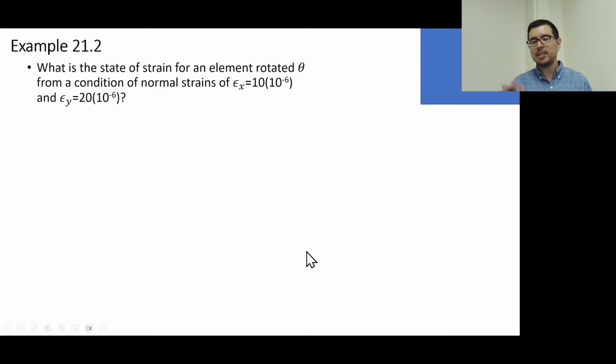Megapascals, microstrains, right? These are kind of flipped ideas. Mega is 10 to the 6, micro is 10 to the minus 6. And it makes sense because you have sigma equal to E epsilon, and E is typically 10 to the 9th. That's the ratio we typically see. We're dealing with microstrains and megapascals, and typically 100 microstrain is in the realm of 100 megapascals, right? Those types of things work out.